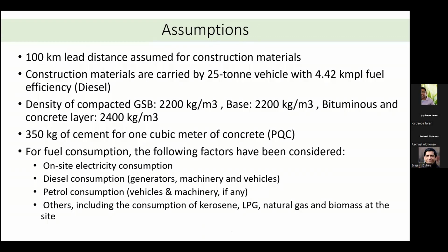So that's the boundaries for cradle to grave, cradle to cradle, where you use the raw materials, then process them, lay a road, then use that particular road, then the complete flexible pavement comes to a maintenance stage. Then you grind it using full depth reclamation, and the recycled asphalt which has been collected is used for laying that particular road. That means you are avoiding all the upstream steps. The raw material extraction and processing were all excluded. That means avoidance has been taken into account here. So such cases can be considered.